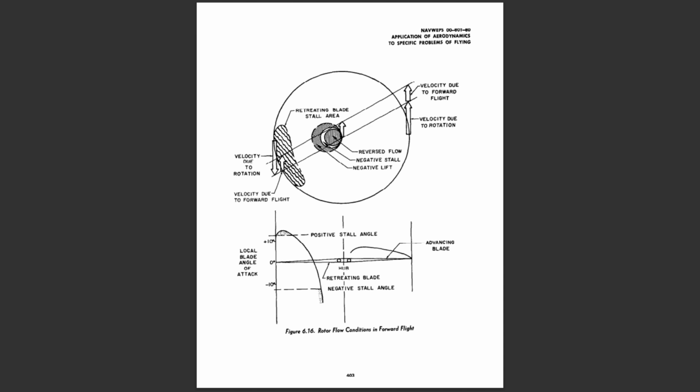The seesaw, or semi-rigid rotor, corrects the lift dissymmetry by rocking the entire hub and blades about a gimbal joint. By rocking the entire rotor system forward, the angle of attack on the advancing blade is reduced, and the angle of attack on the retreating blade is increased. The rigid rotor must produce cyclic variation of the blade pitch mechanically as the blade rotates, to eliminate the lift dissymmetry.